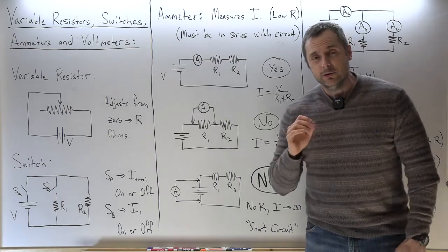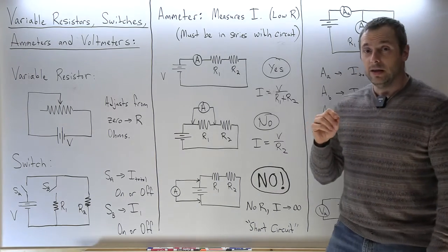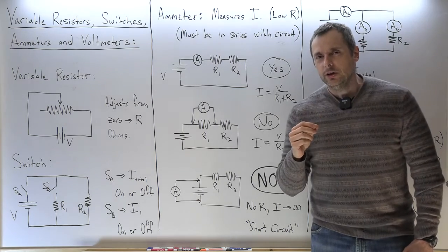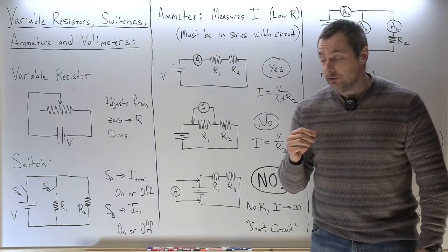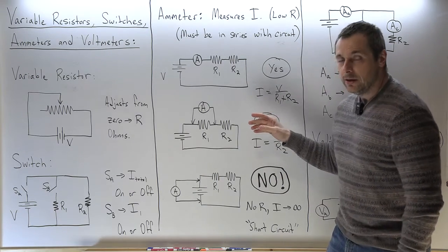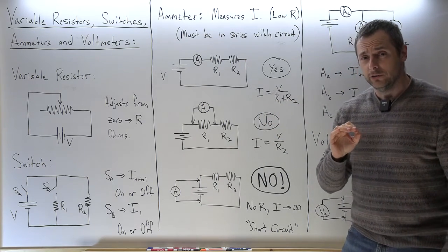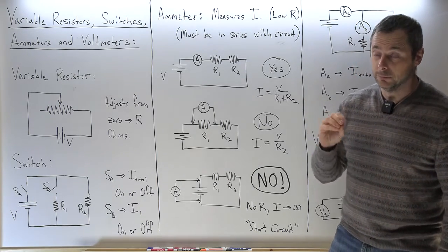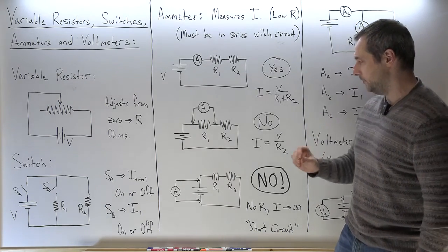But the difficult thing with an ammeter is that because the resistance is low, there's a danger where you could actually cause damage. This is showing an improper setup that doesn't actually cause damage to the meter, but nonetheless causes the circuit to become distorted and give you the wrong measurement.